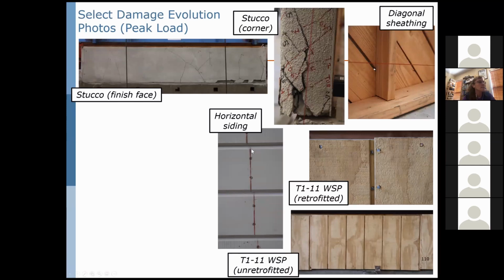You can see that this stair stepping, an indication of the rotation and withdrawal active in the movement of the horizontal siding. You can just see in the T1 retrofit application case for this lower right figure, the rotation of the single 4-foot panels as the stair step is evident, the interface between those panels.